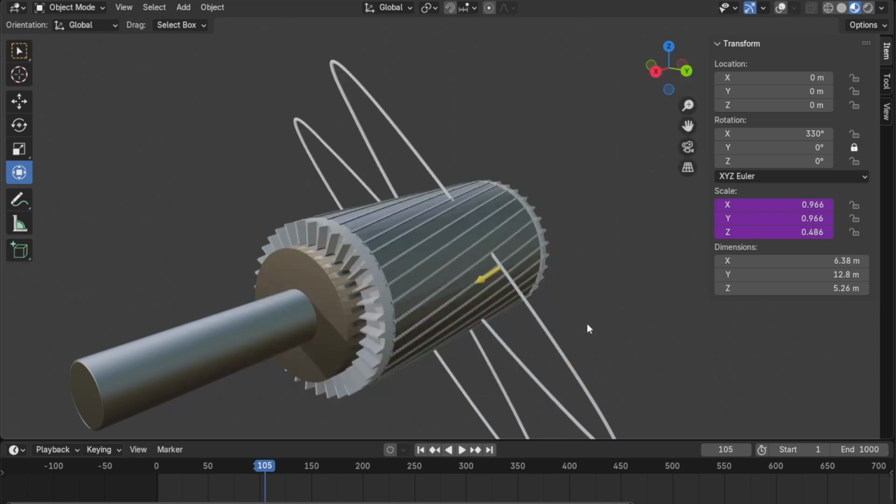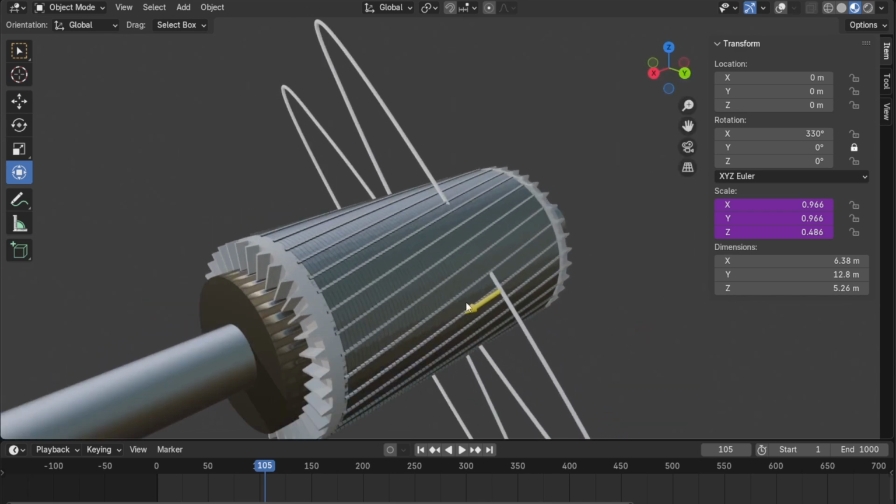All right. So let's think about this for a second. We have these conductive bars here, and they're shorted between these two end rings on either end. And what happens to a conductor when you have a change in flux? You know, when there's flux cutting across it, what happens to that conductor? You're exactly right. It has current induced into it. Actually, it has EMF induced into it first. But since these rotor bars are just dead shorts all the way around, that EMF immediately turns into induced current.